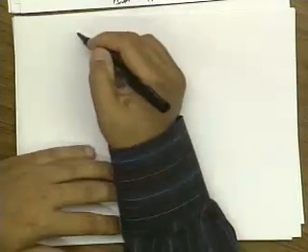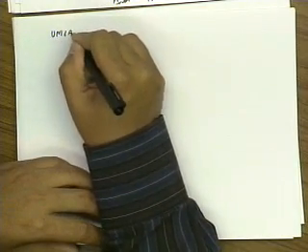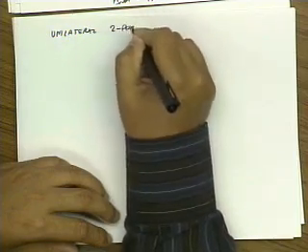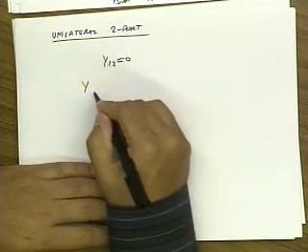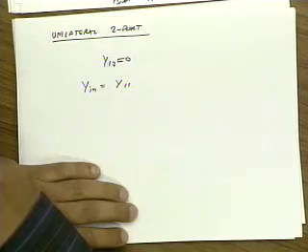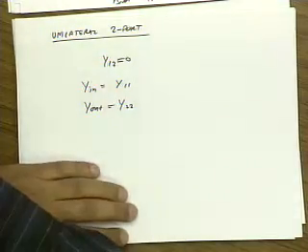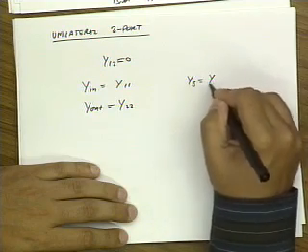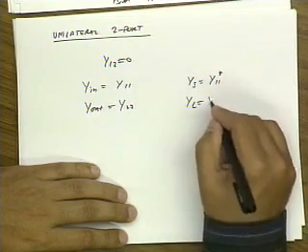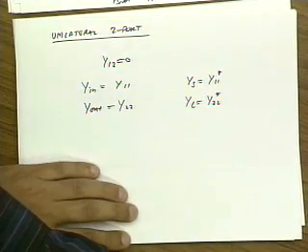Before we go into the gory details, let's solve a simpler problem, just to get some intuition for the solution. So let's look at a unilateral two-port. For a unilateral two-port, y12 is equal to 0. That means that y in is simply y11, and y out is simply y22. So it's trivial, right? To get a complex conjugate input and output match, I simply make YS equal to y11 conjugate and YL equal to y22 conjugate. Make sense? Very simple.